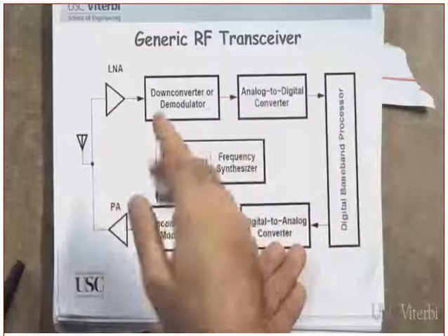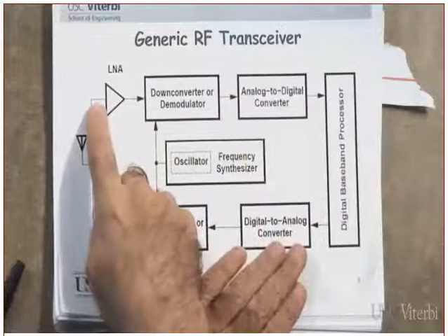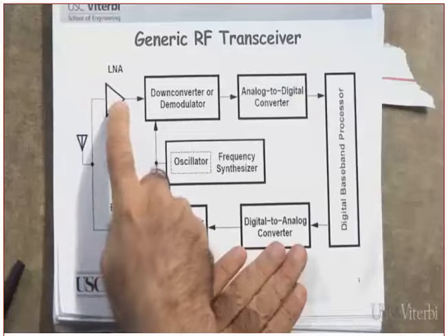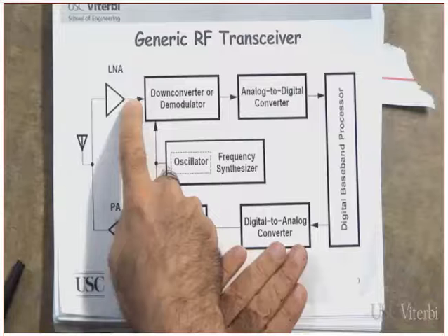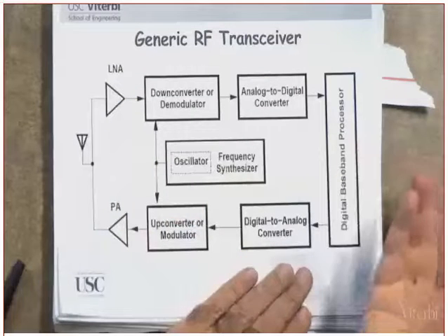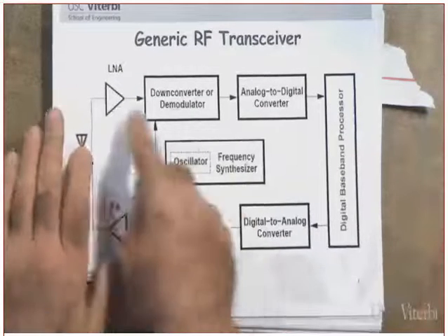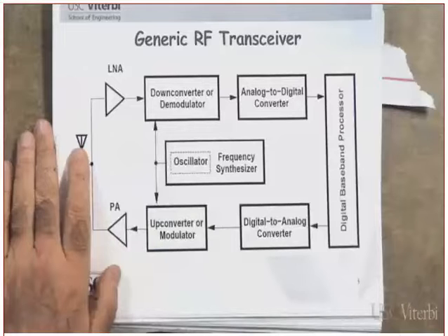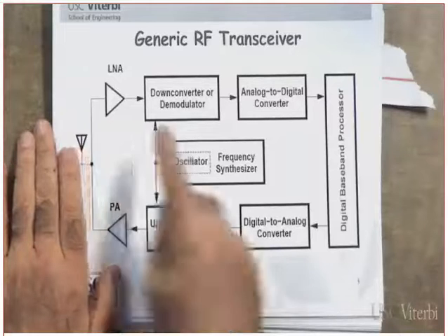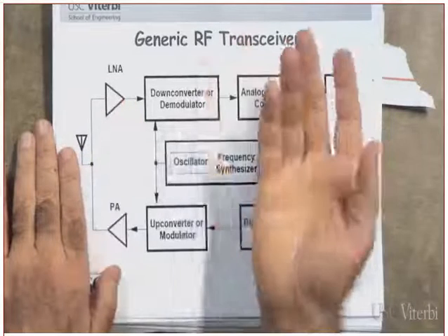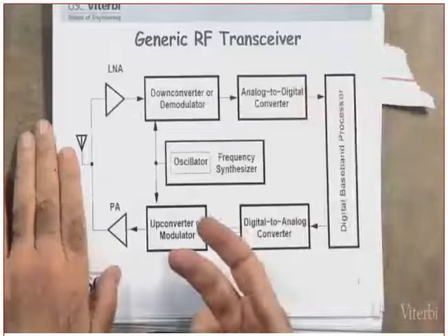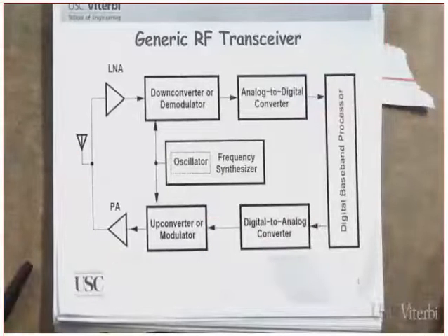Now let's assume, forget about dB, let's make things simple. Let's assume the signal to noise ratio here is 5. If you use an amplifier with gain of 2, what should the signal to noise ratio here be? Why double? Why? You are amplifying both the noise and the signal. So if the ratio here is 5, the ratio in here should also be 5. They found it to be lower than 5.